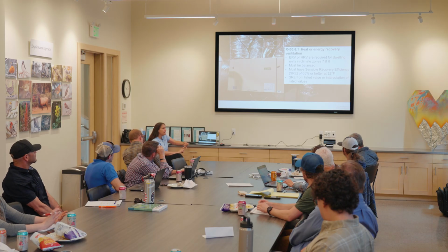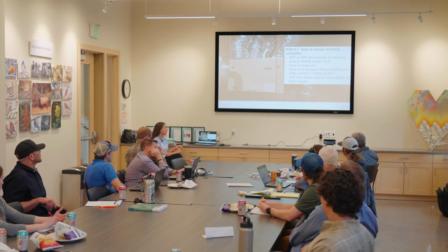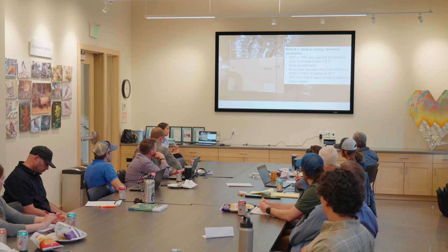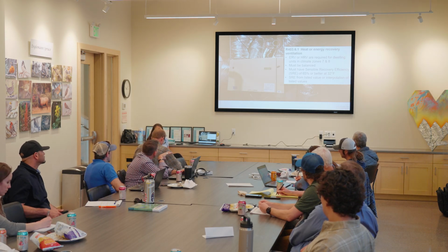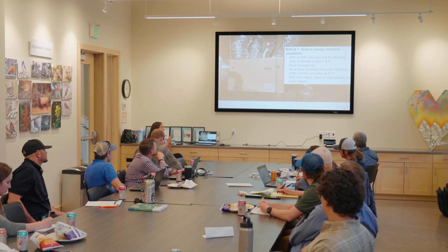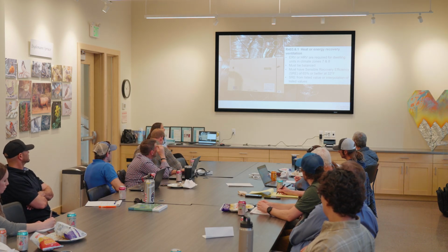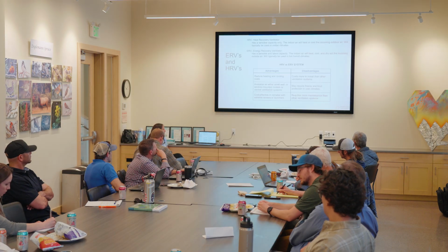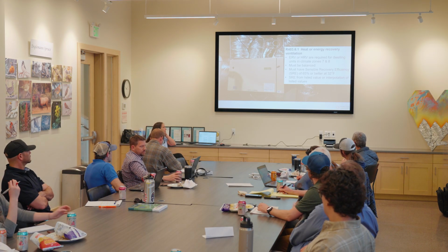Now, the thing that is important is it's not just having an ERV or an HRV. You also have to ensure that your sensible recovery efficiency is at least 65% at 32 degrees. And you usually see that it'll have information here maybe, and I don't think I put it on here. Oh, I probably did here in just a moment.